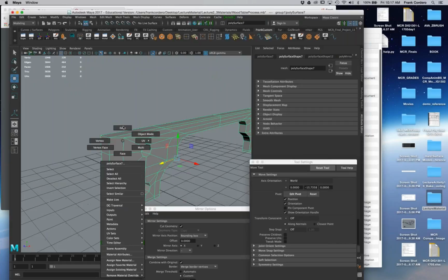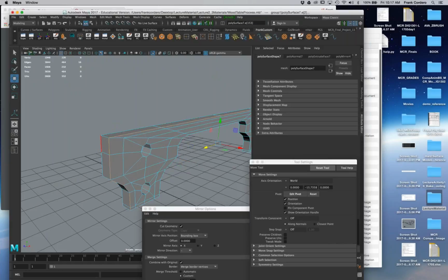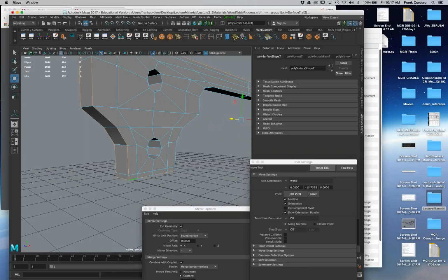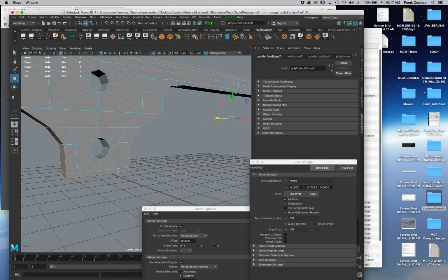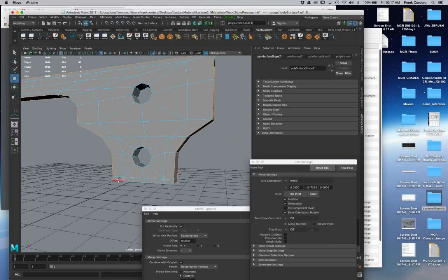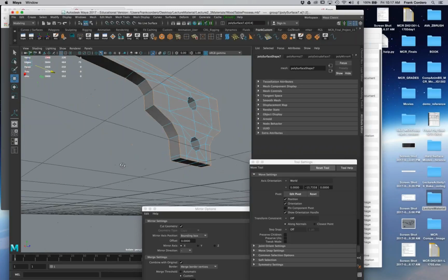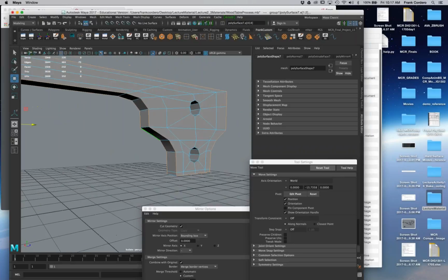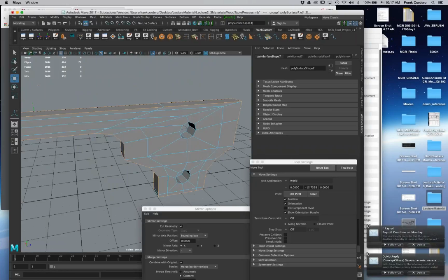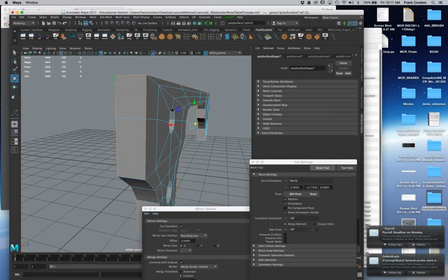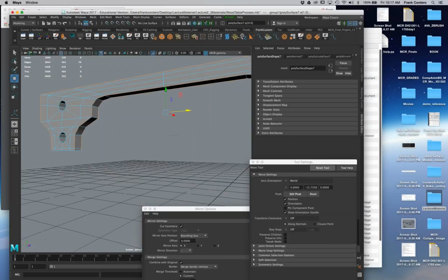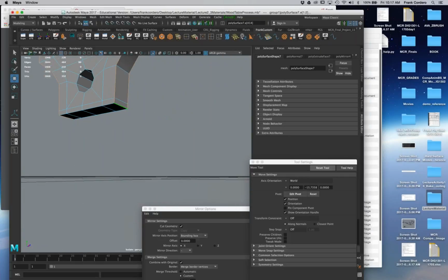So I'm going to go ahead and bevel this, guys. I'm going to bevel all these shapes. And the good news is that it should be fairly fast to bevel because my edge flow is pretty strong in terms of the way these things are coming together. Probably going to need an edge here, an edge here, edge there. Edge here, edge here. All the major transitions.